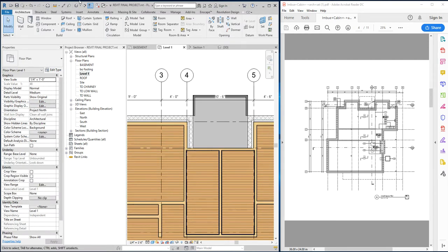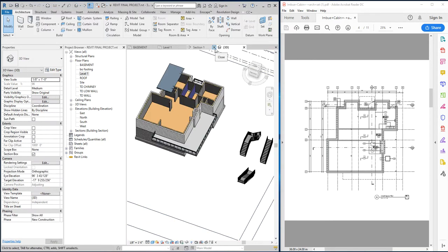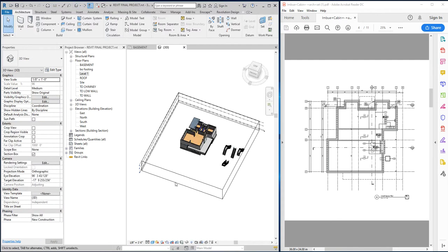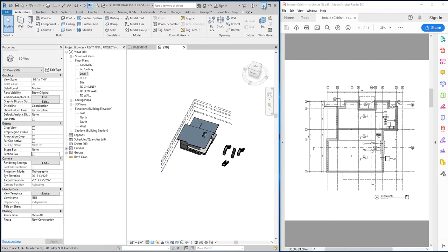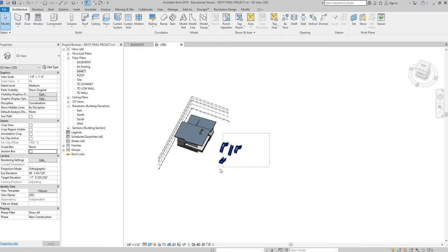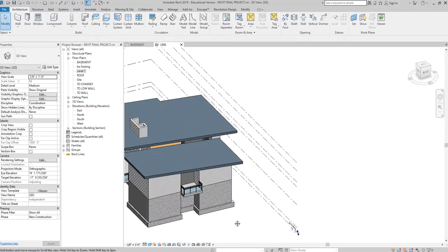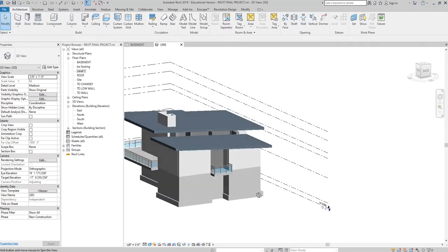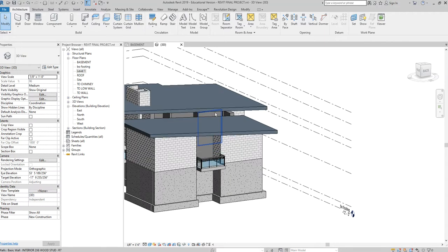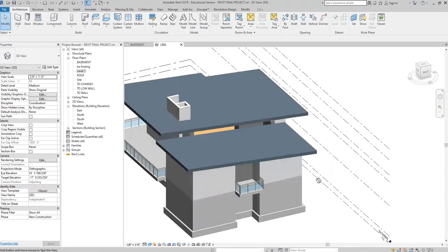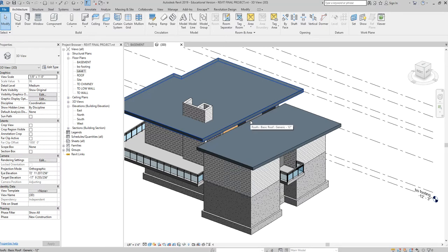Okay. So there's a little problem with this model, right? The problem is that we have a little gap, right? These two roofs, and they are two separate roofs, they're offset a little bit, right? So we have this little gap in there where nothing happens. And so we need to put something there to cover that, right? This is actually a pretty common thing that happens in Revit models, funny enough.